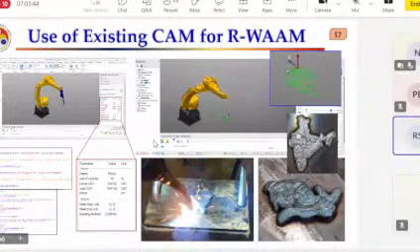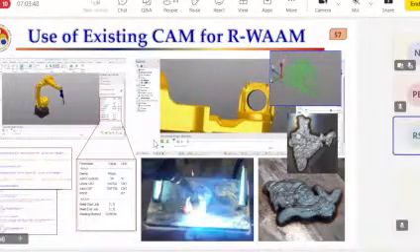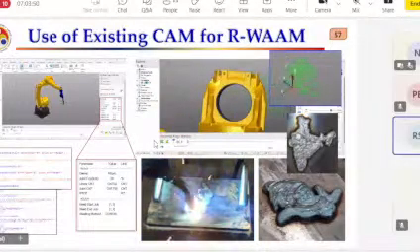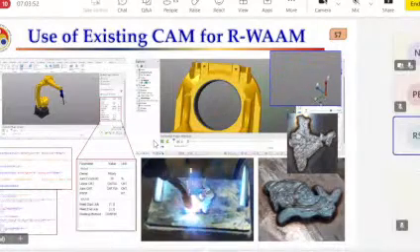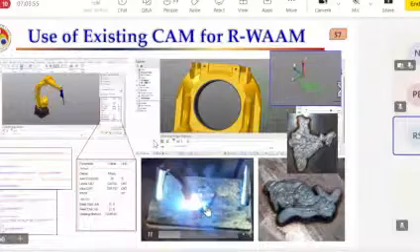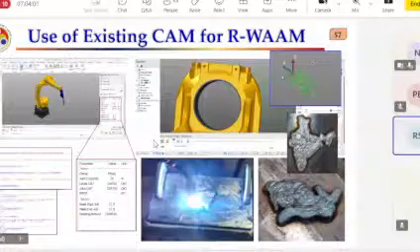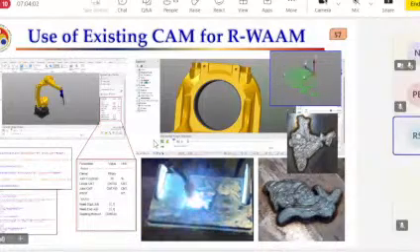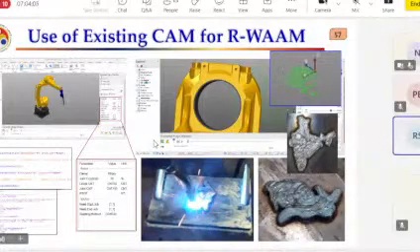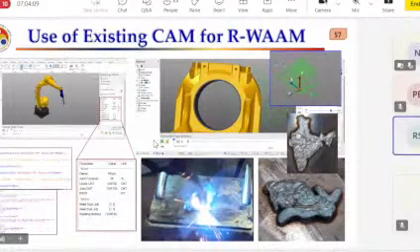At each point you have to calculate the corresponding joint angle. It is not a good idea to calculate it manually for complex shapes; in this case, there are more than 10,000 to 20,000 points in this part. Calculating the angle for each point would be very tedious work, so we need to rely on software such as this robot plugin.